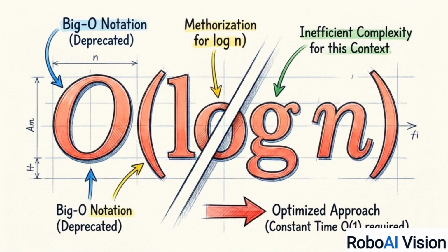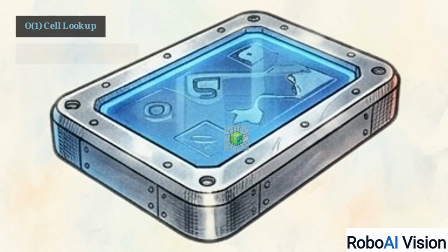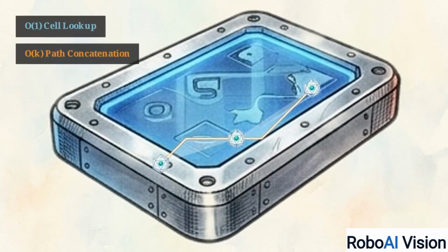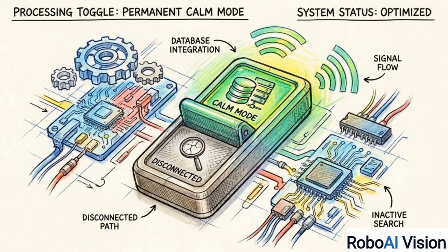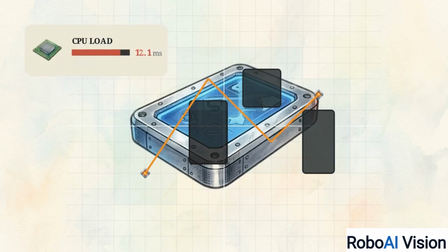This happens because the system no longer executes an active logarithmic graph search. Finding a route becomes a near-constant time operation, requiring only a quick cell lookup and the concatenation of known coordinates. That 9.3 times speedup shifts the initial planning phase entirely from active search to passive retrieval. This frees up the tight computational budget required for the next mathematically demanding step, dynamic trajectory smoothing.